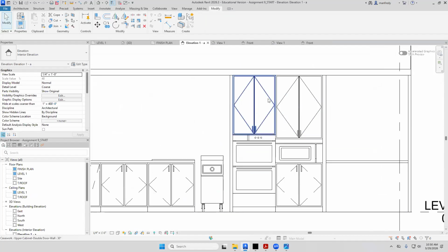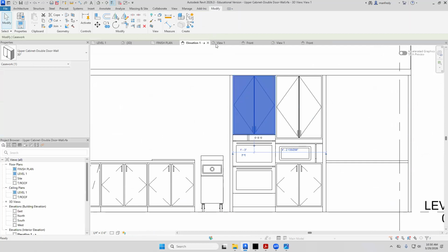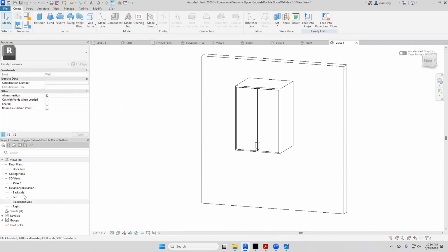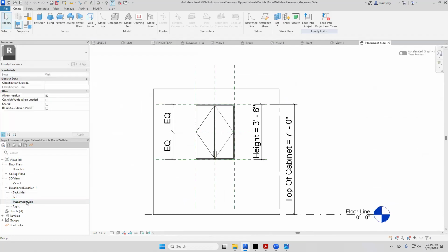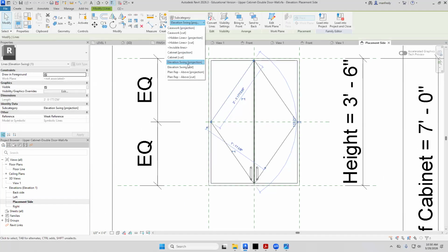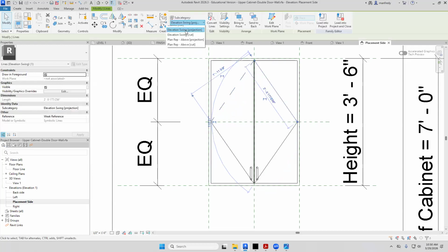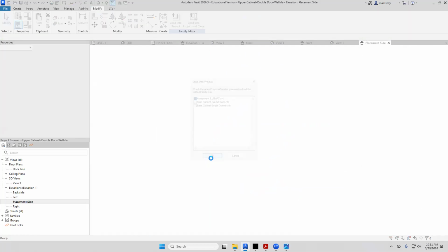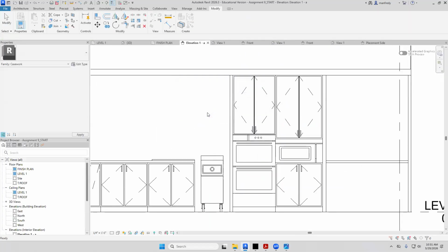Same problem here. This doesn't have the same style. So I'll click on this object here, go edit. Look at the front view. This is the side. Let's see, the front would be this one here. Click on this line here. It's currently called something swing. I'm going to try hidden line projection instead. And hopefully I get to the style I'm after. Load it, accept it, overwrite it, there.